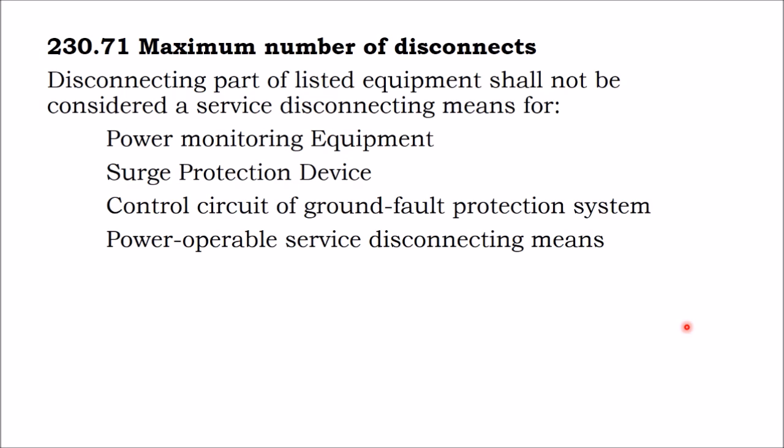Maximum number of disconnects. Disconnecting parts of listed equipment shall not be considered the service disconnect for power monitoring equipment, surge protection devices, control of a ground fault protection system, or power operable service disconnecting means.